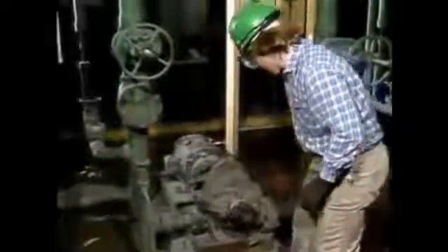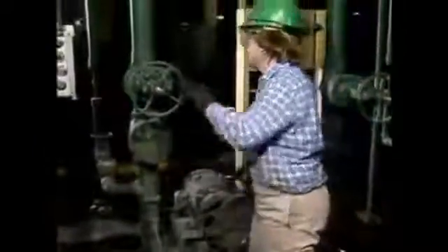Here, he checks the bearings to see if there are any oil leaks. Finally, he looks over the pump's discharge piping for the same things as with the suction piping. If he finds a leak, he'll trace it to its source and then report it to his supervisor.